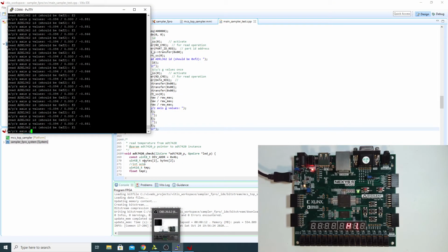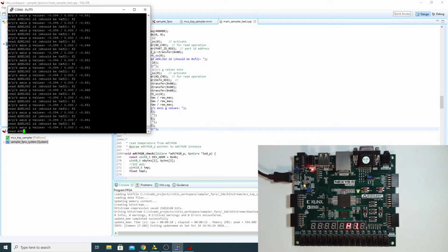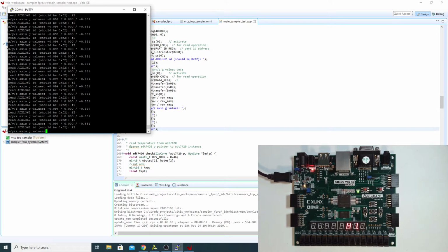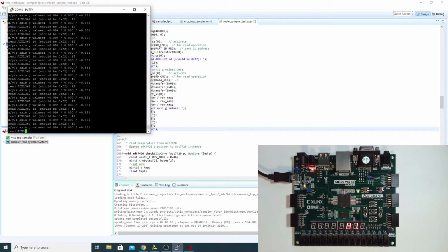I have opened the UART, the terminal, the console, and as you can see, it's actually sending data nonstop, and it's very difficult to read it. And the indication that it's actually sending stuff over the UART, you can see it on the board, is here. That little LED here is almost always lit, because it's super fast. So we need to slow it down a little bit.